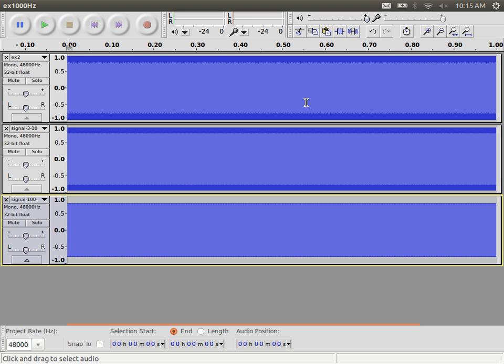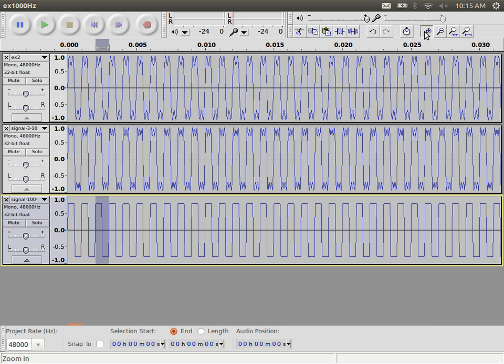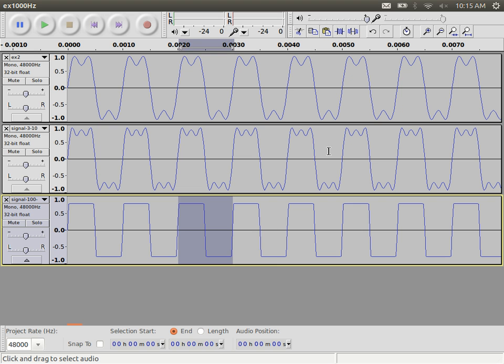Zoom in. There's our much more accurate signal, just combining 100 sine waves together using this pattern: 1/7 sine 7 times 2000, 1/9, 1/11, and so on, up to 100 components, and we get almost a perfect square wave here. If you add an infinite number of components, it will be the perfect square wave, in theory.